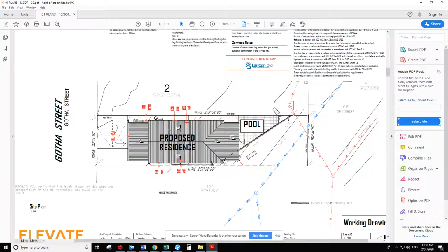where we can position the house on the block and where it needs to be for different levels, and also if we need additional drainage from the different heights. So it's much higher up here than it is down here. You can see from this number here is 34.16, and then it drops off to 31.10 at the back of the block, so much lower.